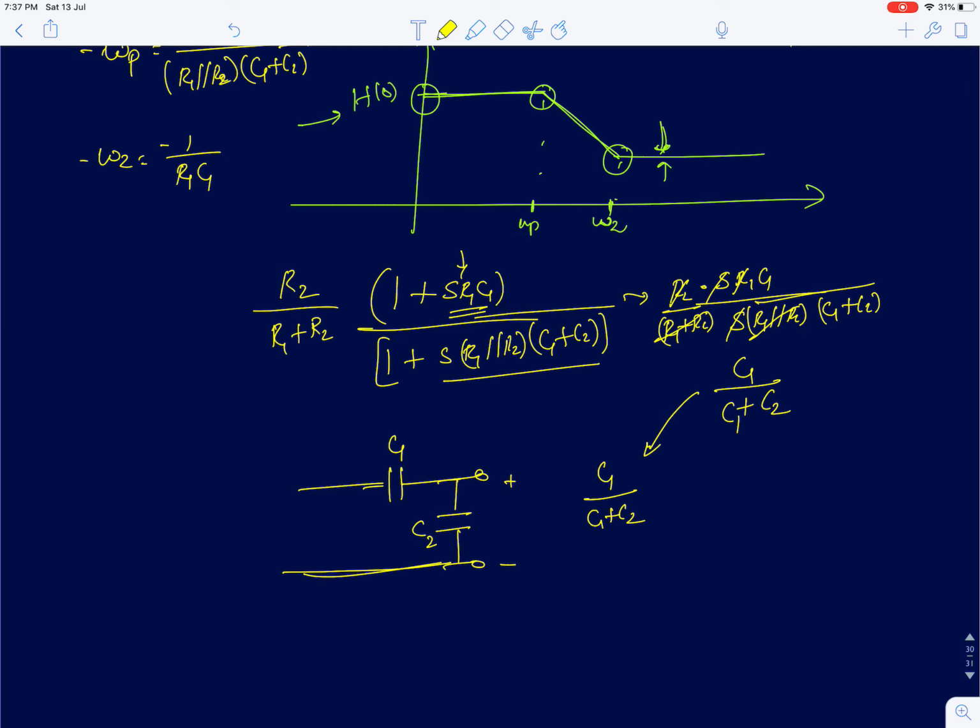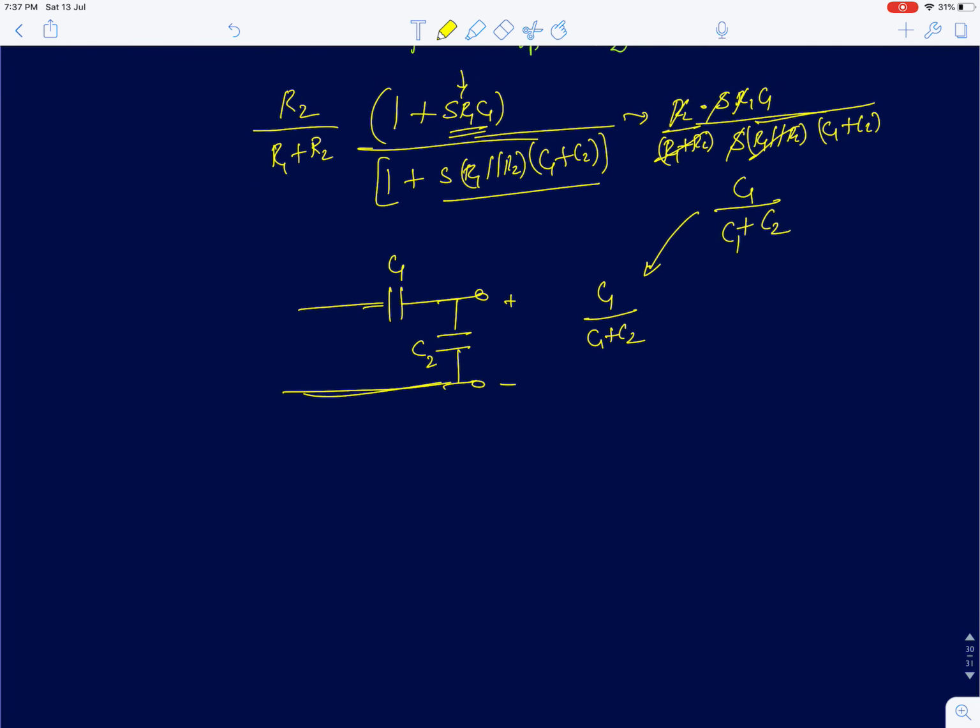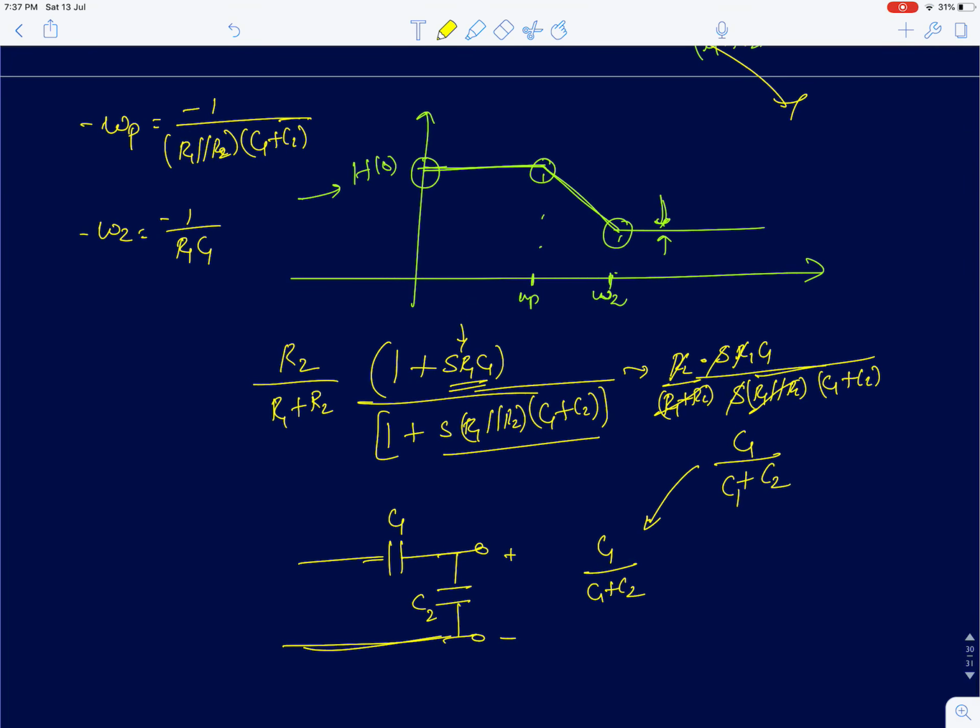As I said, if you know the DC low frequency transfer function and the poles and zeros, the high frequency gain is automatically determined. It can't be a different number. It's dependent on these three parameters: the low frequency gain, the pole, and the zero. That's it. Now, how to find the transfer functions for systems with 1 0.